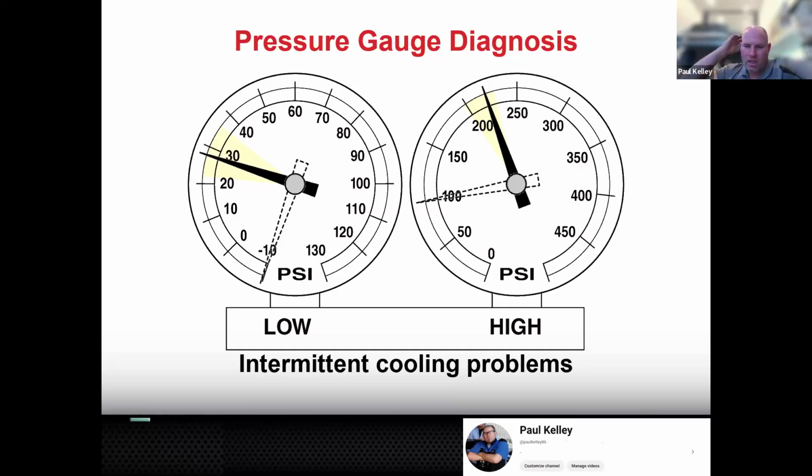Full airflow though. So the evaporator freezing over externally, cool idea, but that would make a low airflow volume. And I did tell you that story in that version, but this version is a little bit different. This has full airflow. This is actually moisture in the system. It hits the TXV. The TXV freezes the moisture. There should not be moisture in there, but it's freezing.